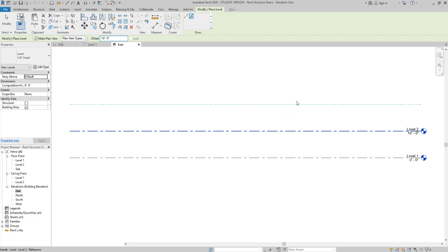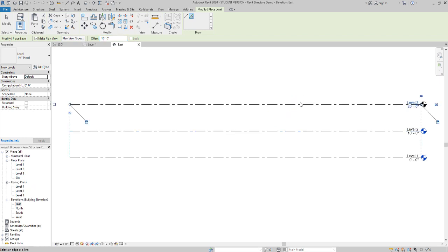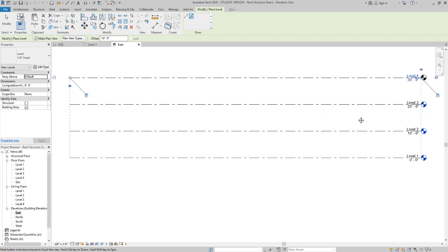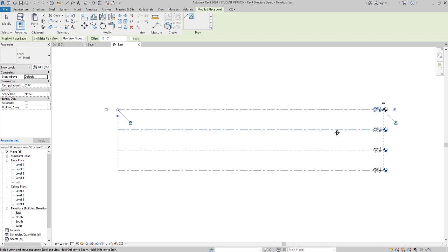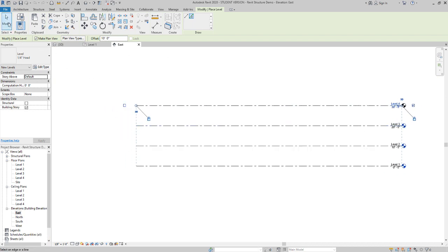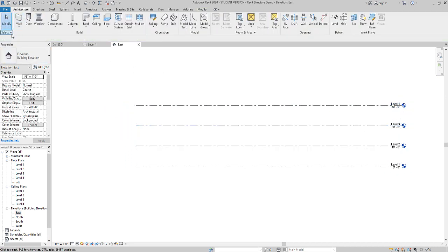And we're going to just select the line below where we want to go. Notice that there's a little dash line that pops up as a preview for your offset. And that's true with anything that you offset in Revit. Click on the Modify button. That's what they mean in the directions. You could also hit Escape twice. I keep my left hand over by the number keys, the A, S, D kind of key row, and I hit the Escape key with my left hand quite often.